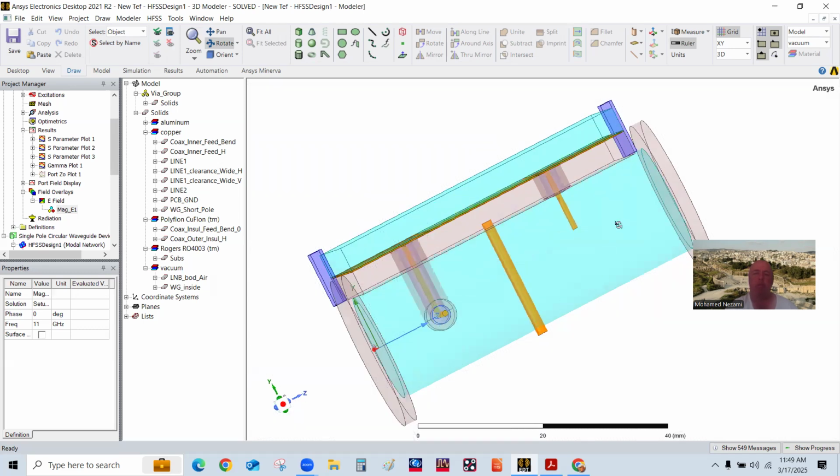So the signal comes in here and gets picked up by the vertical pin, the probe. If anything leaks past that, it gets reflected back off this quarter wavelength back short. It goes a quarter wavelength out and back, 90 degrees and 90 degrees, so it's 180 degrees in phase, and it sums up.